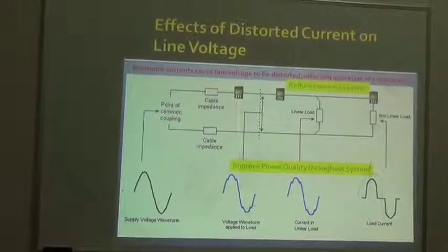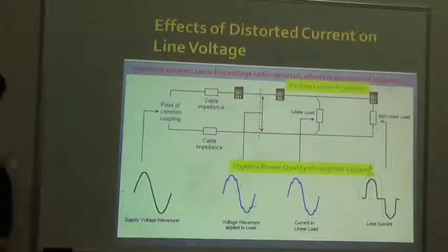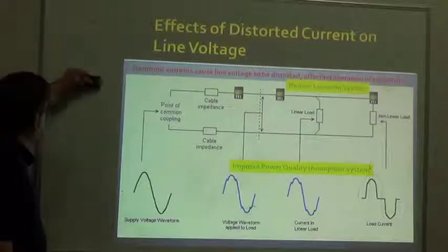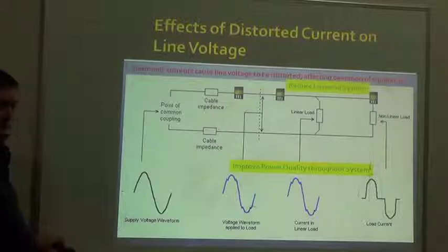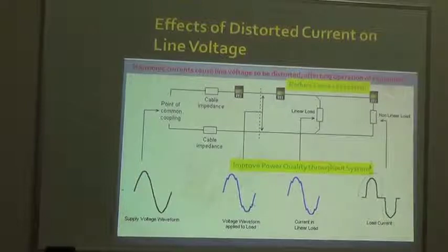But it will demonstrate that the SP1000 works. If you want to do it in stages, correct me if I'm wrong, Philip, you put it on that sub panel and get the reads off the dashboard of the SP1000 and compare them to the reads on the meter. You can turn the capacitors on and off within the SP1000, correct? So you turn the capacitors on, it runs for an hour or whatever, and you measure before with the meter, and then you put the SP1000 on and measure with the meter along with it, so you have an independent read and you have the SP1000.